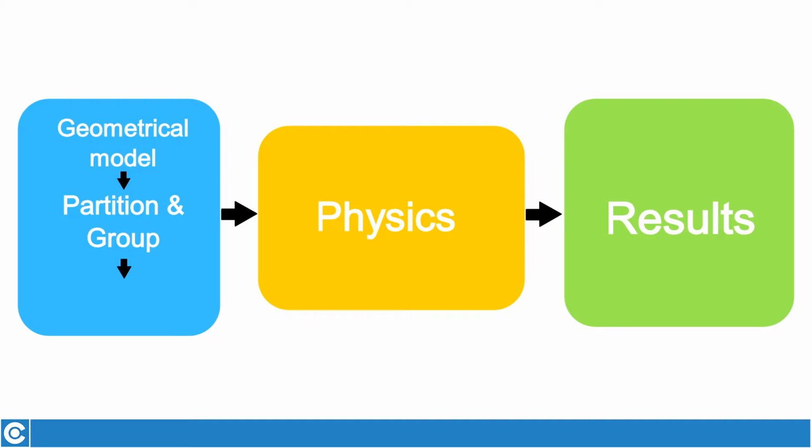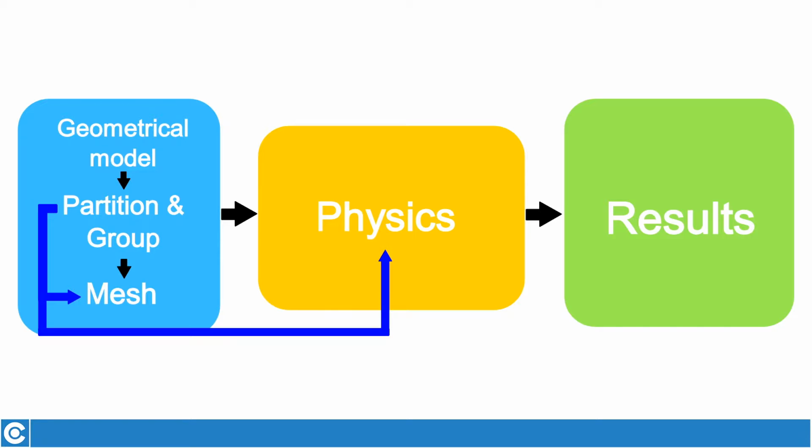This step is very important because the names and parts created in this step will be used for mesh creation and physics definition. In the last step, you prepare your simulation domain for calculation by creating a numerical grid, which is known as meshing. The rest remains as we discussed previously. After geometry definition, we define the physical side of the system, such as frequency, current and materials, and when the system is completely defined and calculated, predictions about physical phenomena such as heating will be presented.